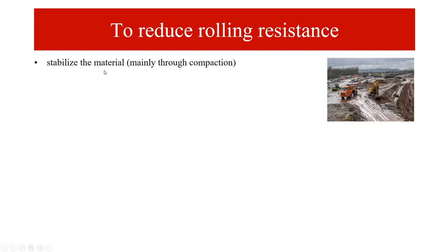First thing is stabilize the material, okay? The more stable your material is, meaning when they are tough, when they don't move under the tires, then there will be less power required to move over the surface. In other words, there will be a lower rolling resistance.